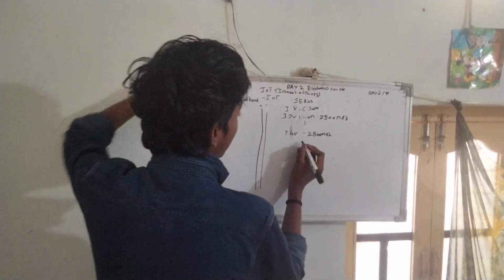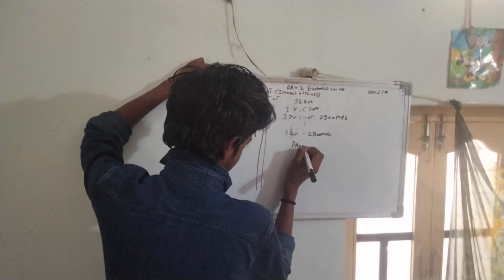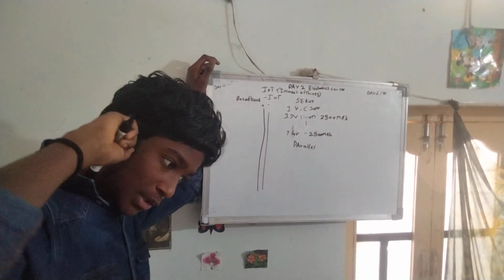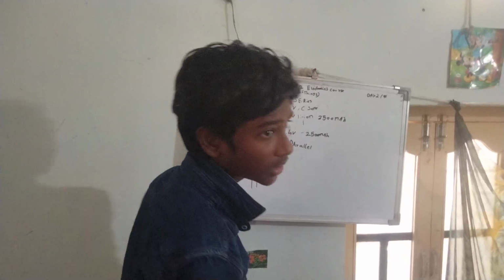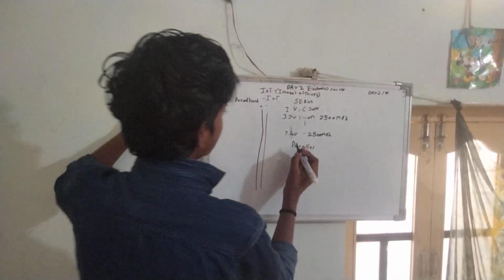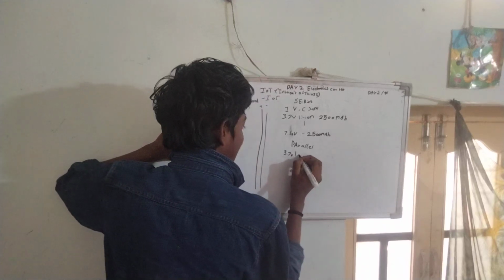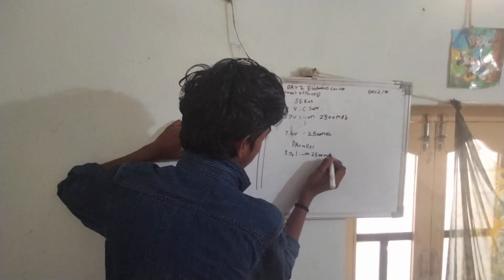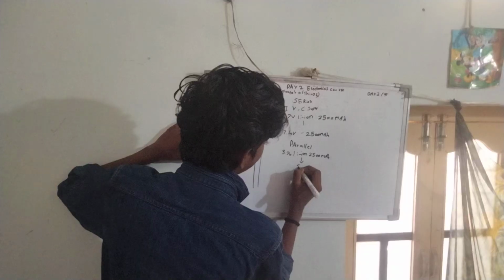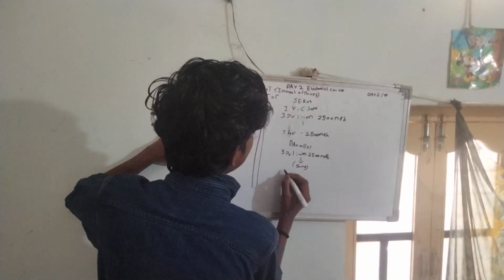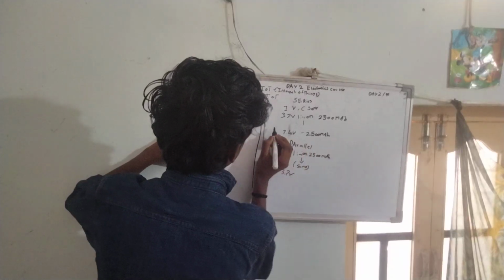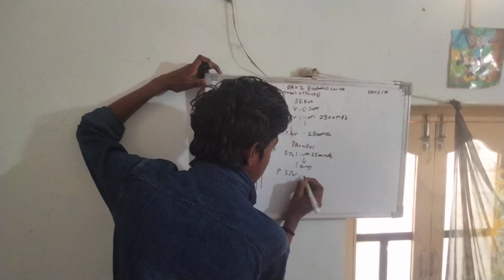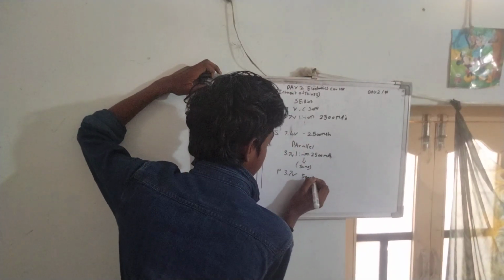Now, next comes the parallel connection. This is one more important connection when we need to increase the capacity of the battery or current, but keep the voltage the same. Again, we take the same example of a 3.7 volt lithium ion battery of 2500 mAh. If I connect it to one more battery of the same, I get 3.7 volts. Unlike series, I get 3.7 volts in parallel connection. But here's the twist: I get 5000 mAh of capacity.